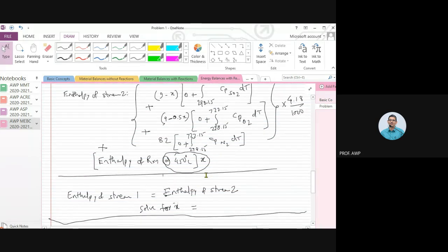So Atharva is saying that he has already considered the enthalpy of reaction, and the reaction is occurring at 450 degrees centigrade. Therefore, he does not need to consider SO2 and SO3 separately, because this enthalpy is automatically there as X moles of SO2 gas plus 0.5 X moles of oxygen gas, giving you SO3 gas. This is automatically there at 450. He has only considered that the reactants are at 450 degrees centigrade and they get converted to SO3 at 450 degrees centigrade. Yes, sir, I understood.